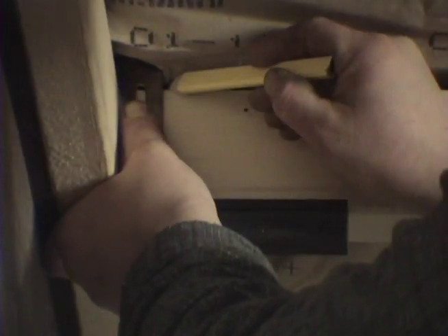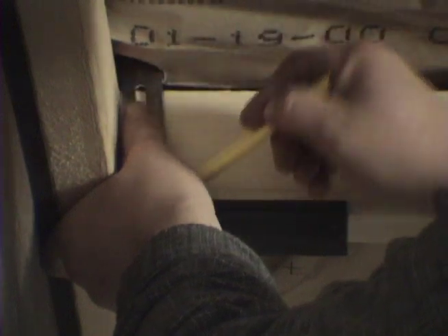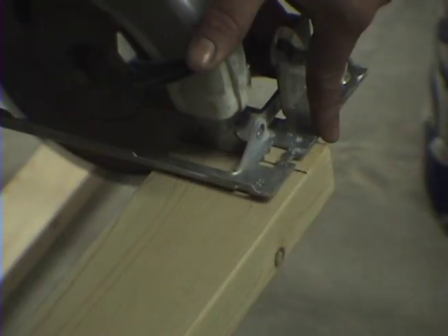Now we need to cut the angle for each 2x4 we will hang. We know our angle is 1.67, but it pays to put each 2x4 in place and mark the actual angle with the angle tool and then trim off the ends.